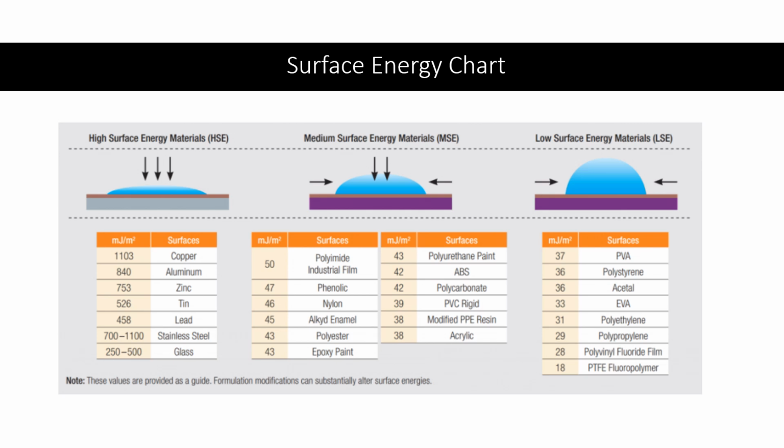So when you're working with all of these materials and these substrates, it's very important to understand what exactly you're sticking to. A lot of our customers will tell us, hey, I'm looking to stick aluminum to plastic. Well, is there some sort of surface on the aluminum? What type of aluminum is it? Is it galvanized aluminum? Is it mill finish aluminum, which is just bare aluminum? Is it painted aluminum? And what type of plastic is it?